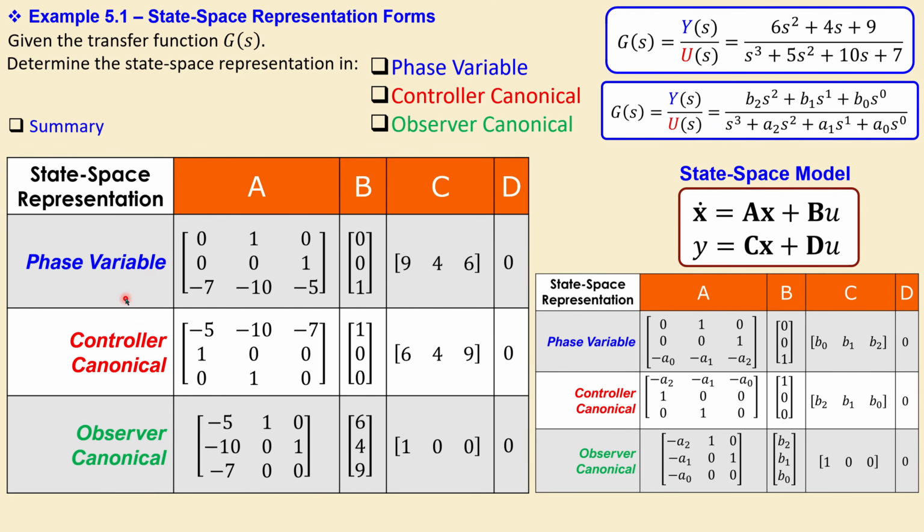It helps also in our design to calculate and proceed in the controller design in a much more efficient way. That's also the reason for the discussion of this state space modeling. In a classical way, we have only one feedback loop. In state space modeling, we have multiple feedback loops, which allows you more freedom, so you can assign or place your poles at any location, which is not possible in the classical controller design.